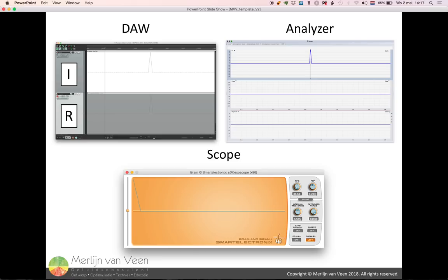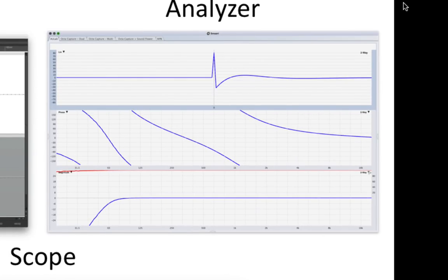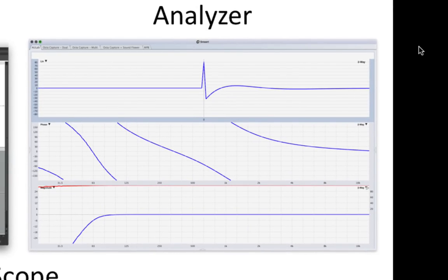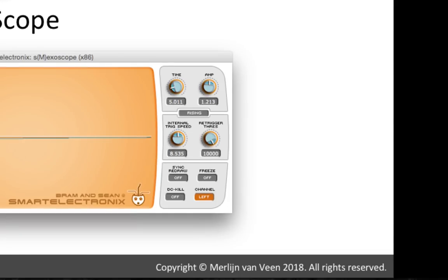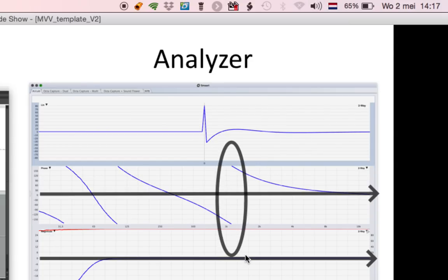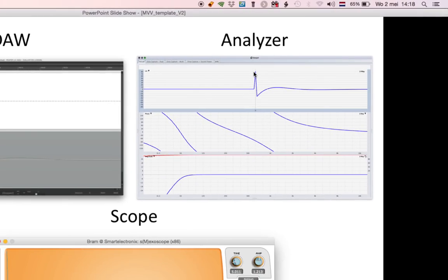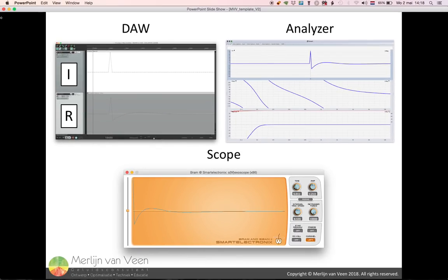Then we changed our microphone cable with virtual processing into something that looks like an actual two-way loudspeaker. This is what I would expect to see when I deal with a regular two-way loudspeaker with a fourth order crossover, somewhere in the vicinity of 1 kilohertz, which is over here. And clearly that impulse response no longer looks the way it did before.